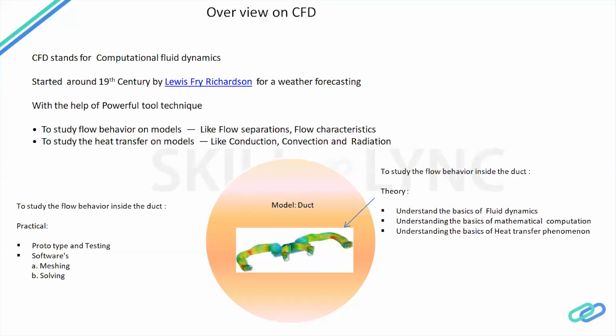Firstly, I am going to explain what fundamentals are available in fluid mechanics. First, we can start with the basic equation called the continuity equation. The continuity equation talks about the mass entering any system being equal to the mass leaving the system. Here, mass in the sense means mass flow rate. So the mass flow rate entering the system is equal to the mass flow rate leaving the system. This is the basic continuity equation.